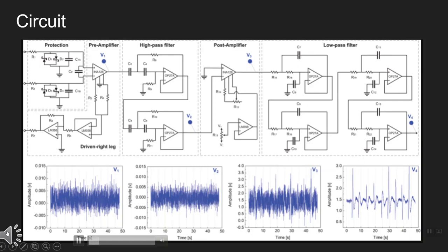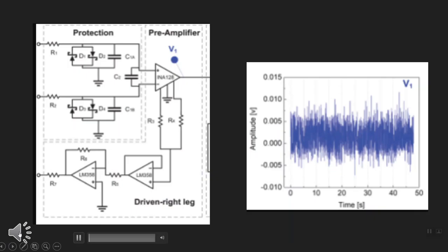The circuit shown here is a single-channel EOG acquisition circuit that is used to capture and analyze horizontal eye movement. The different components of the EOG circuit are labeled for their purpose. The input for this circuit comes from 3 different electrodes placed on the face of the participant, 2 of which are for differential amplification and 1 for reference.